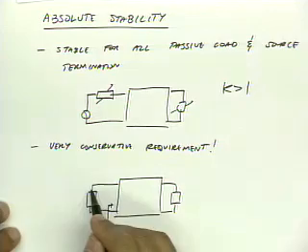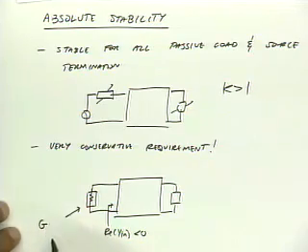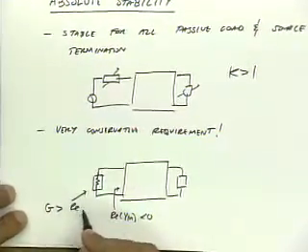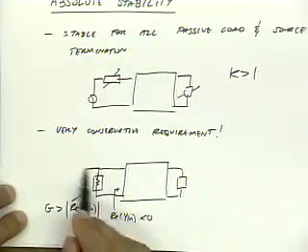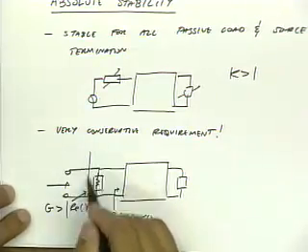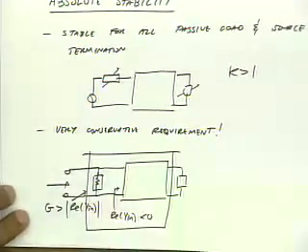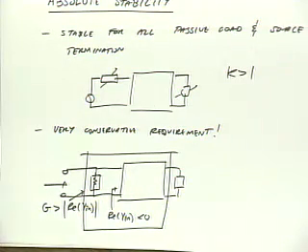If I just add a conductance g which is bigger than the absolute value of real part of y in, then the net conductance now looking into here is positive. So I've created a new 2-port that's unconditionally stable. Okay? And that's actually an important concept. It's going to let us define power gain for systems that are not unconditionally stable.